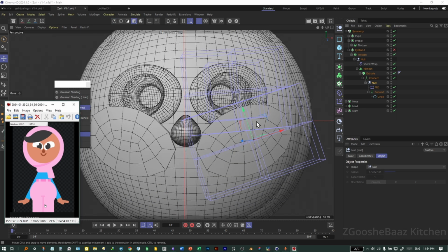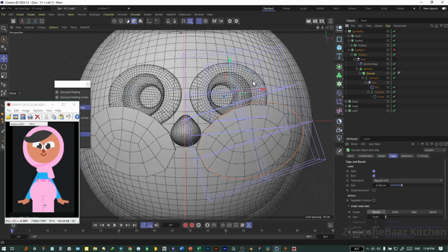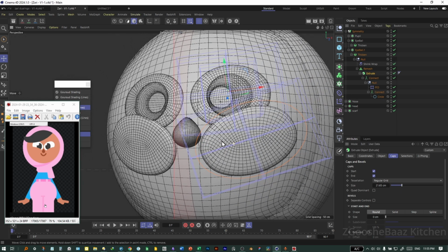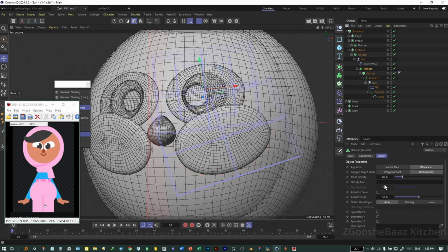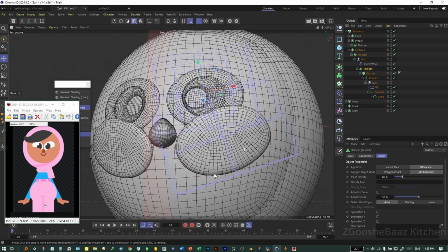So I found a little problem here, and this is a great situation. I can teach you something that wasn't in my script. As you can see, the center axis for this circle, connect, FFD and null are at the same place. But after this, because we changed the position of the null from here, the connect and all other objects have the center axis up. And what's the problem with this? Nothing. Just when we make the object, we cannot use the symmetry option on the remesh generator, and because of this, it is a little bit off.